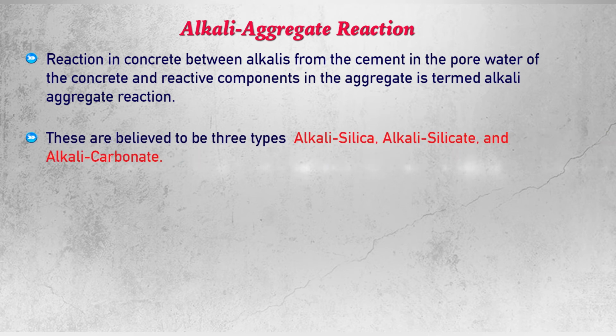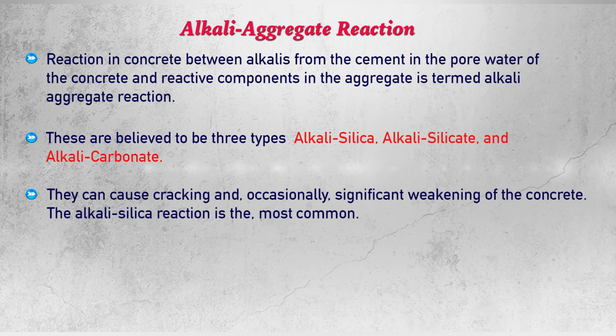These are believed to be three types. First is alkali silica reaction, then alkali silicate reaction, then alkali carbonate reaction. They can cause cracking and occasionally significant weakening of the concrete may occur. The alkali silica reaction is the most common.